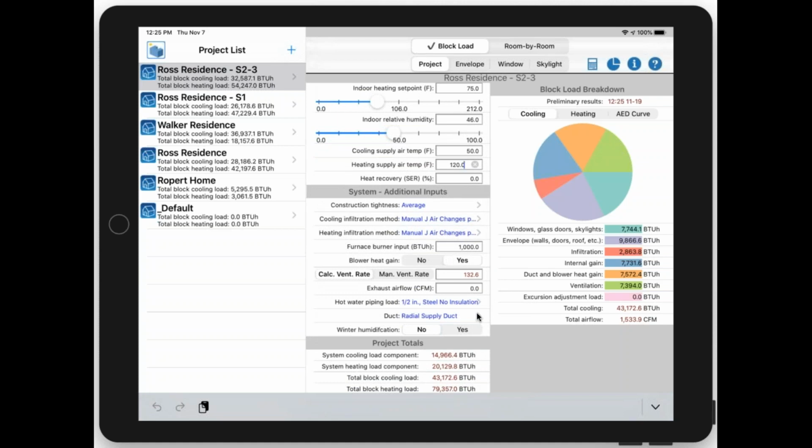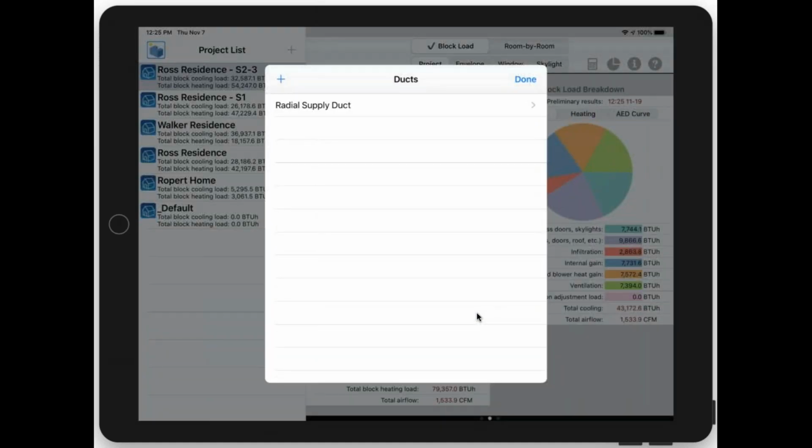All right, let's talk about duct. As you probably know, if you have a leaky duct system in your attic that's not well insulated, it could drastically affect your load. It could add tons and tons of cooling to your cooling load, because as that air is passing from your furnace through that leaky ductwork that's not insulated, a lot of that air is going to escape into your attic and not go where you intended. So there's a lot of waste.